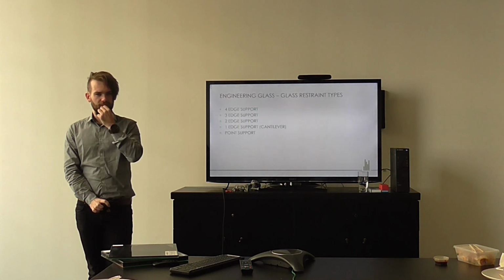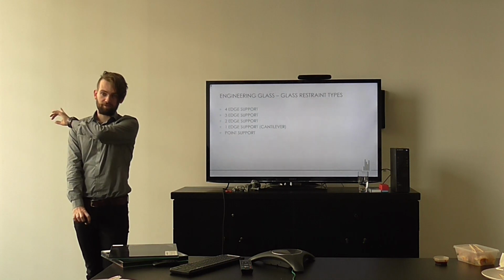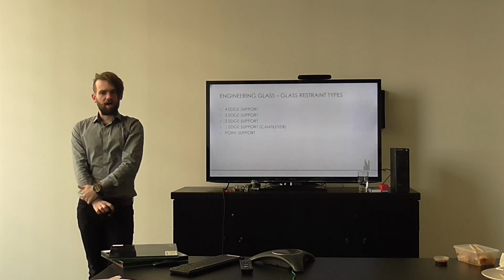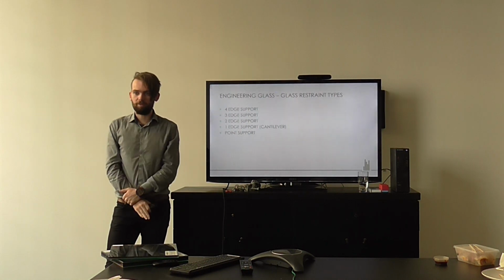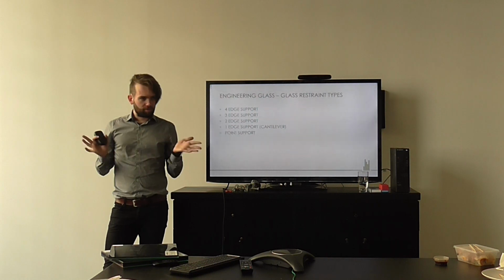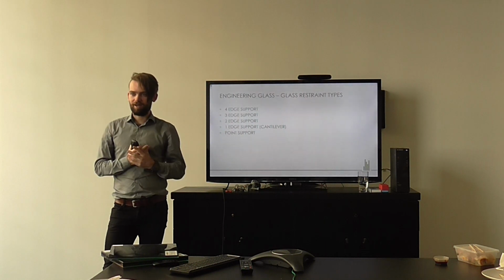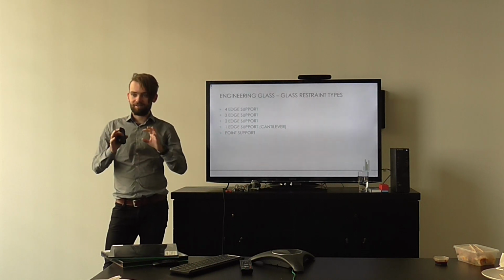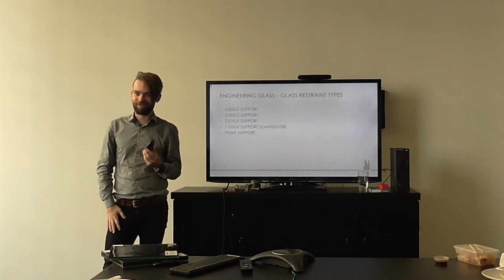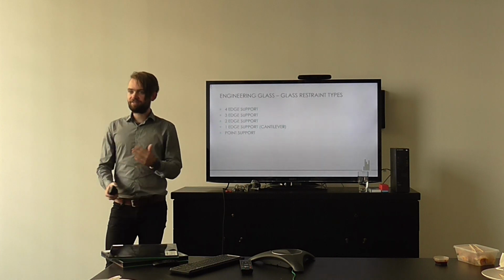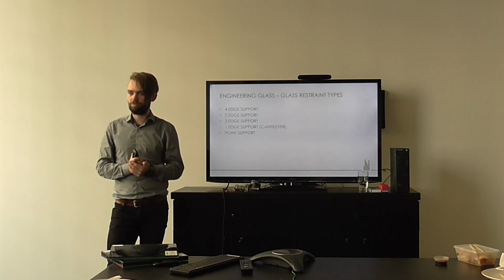Stephen had an interesting project he was involved in with a balustrade over in Carlton, where essentially it was monolithic toughened glass on an apartment building balcony, and for a reason that may still not be fully known, suspected maybe that it had been pushed in and left under stress, dash cam footage captured the panel breaking and falling into the street and narrowly missing some people. So it's things like that that provide a good reason to get it right from the early stage. That's where it should be pushed through.